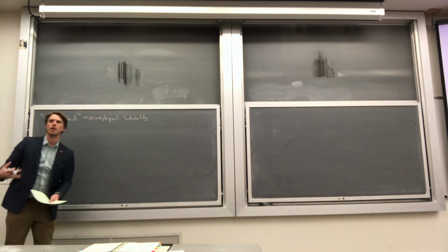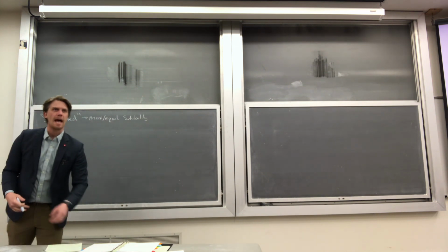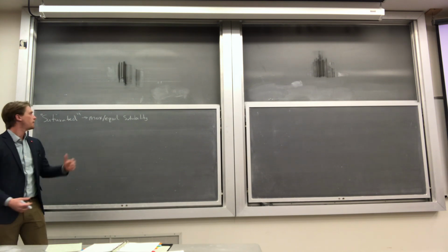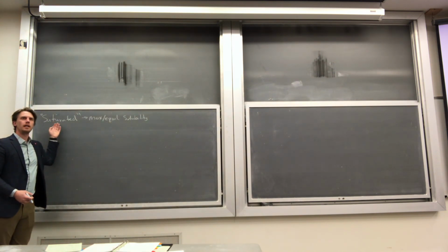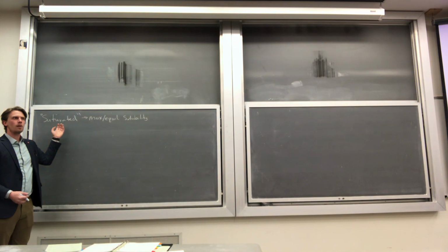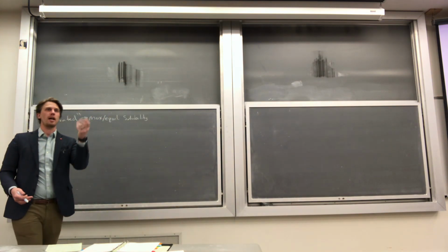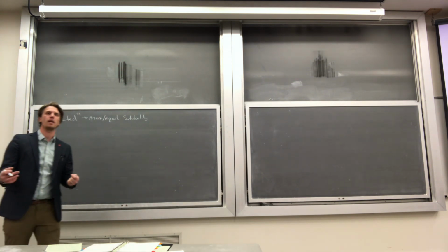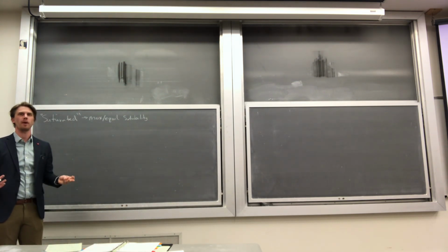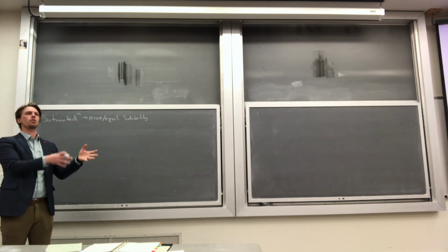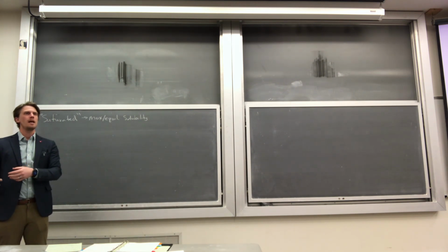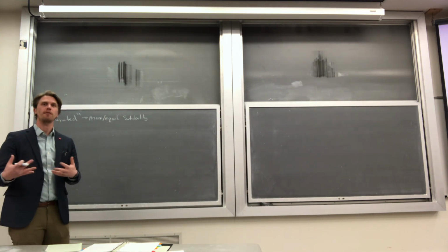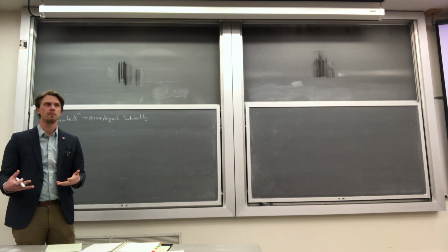Now, generally, when we think of solubility, we'll think of it as salt in water, sugar in water. But this term, saturation, is a generic term in thermodynamics. It can refer to, is the air saturated with water in the case of humidity? Is the system saturated in terms of a PXY or a TXY phase diagram? Just because a certain amount of benzene can dissolve in toluene and a certain amount of toluene can dissolve into benzene, it doesn't necessarily mean you have to be at that equilibrium composition. Okay?